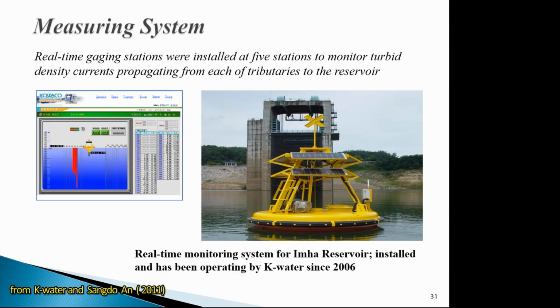Then, of course, they had a monitoring system. It's in general very difficult to measure the sediment concentration directly. So what you try to do: turbidity is easy to measure. And since we deal with fine sediment, you can do a correlation curve between turbidity and concentration of sediment in milligrams per liter. Then you measure turbidity, which is easy to measure, and then you back-calculate what the concentration in milligrams per liter is going to be from that rating curve. Does it make sense?